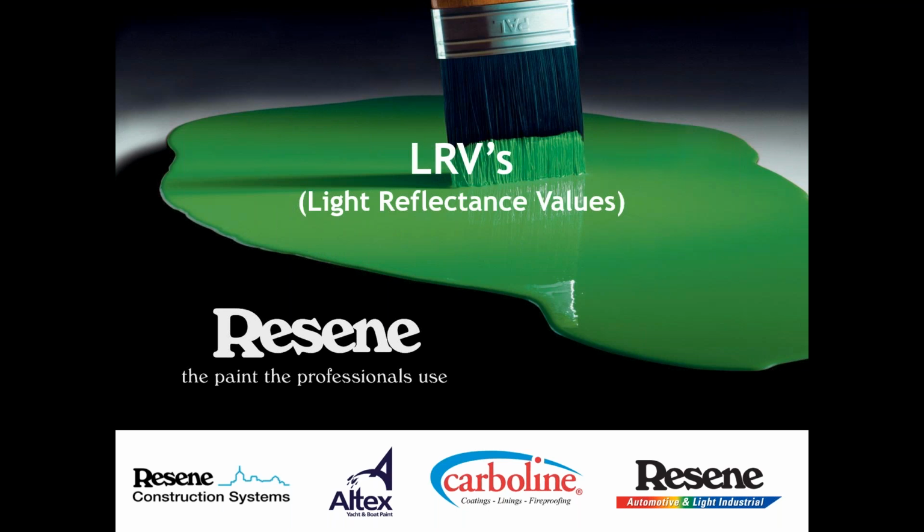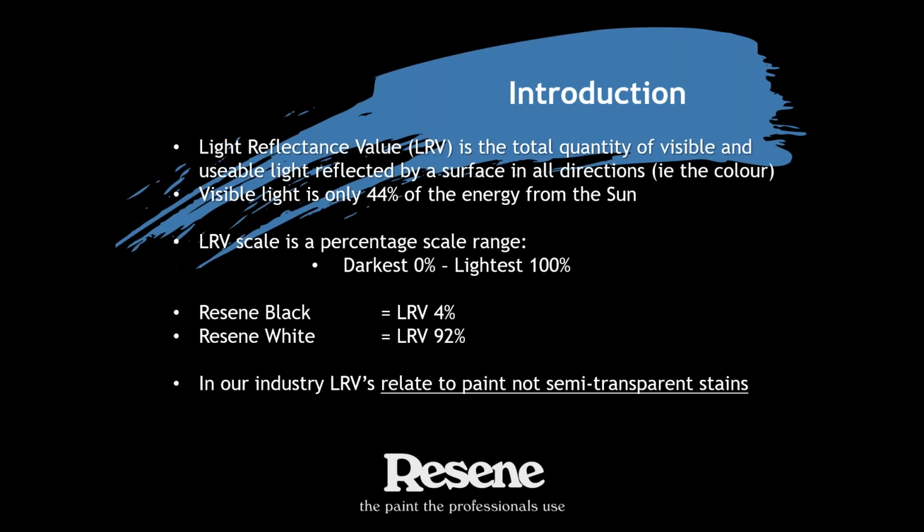So LRVs, light reflectance values. Now, many of you may understand these, but we do get a lot of people coming through a little confused about LRVs. Light reflectance value is the total quantity of visible light that's reflected from the surface. So what that means is it's the color that you see on the surface. Visible light is only 44% of the energy from the sun. 56% is made up by other parts. We'll go through that a little later in a few more slides.